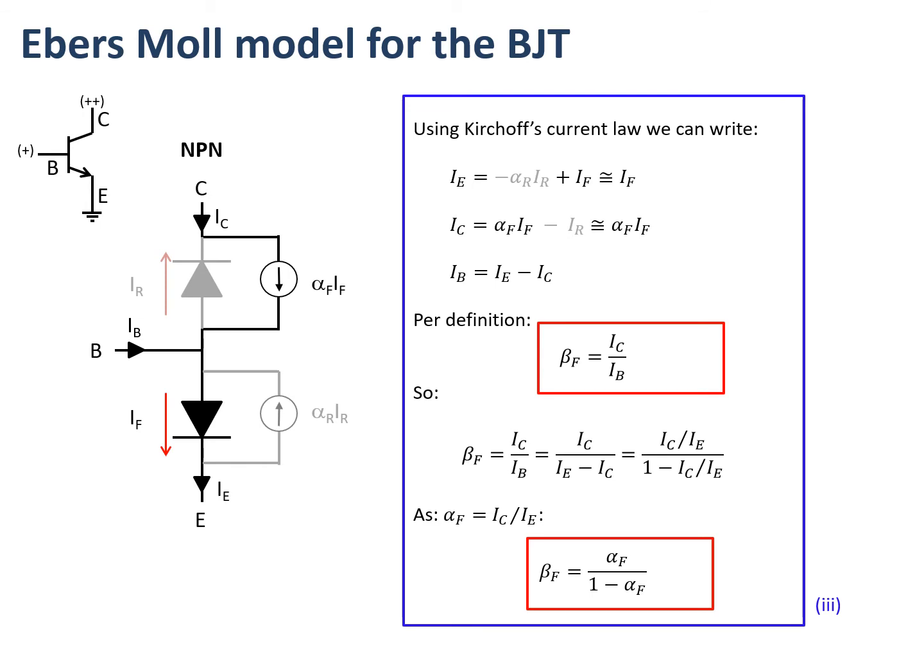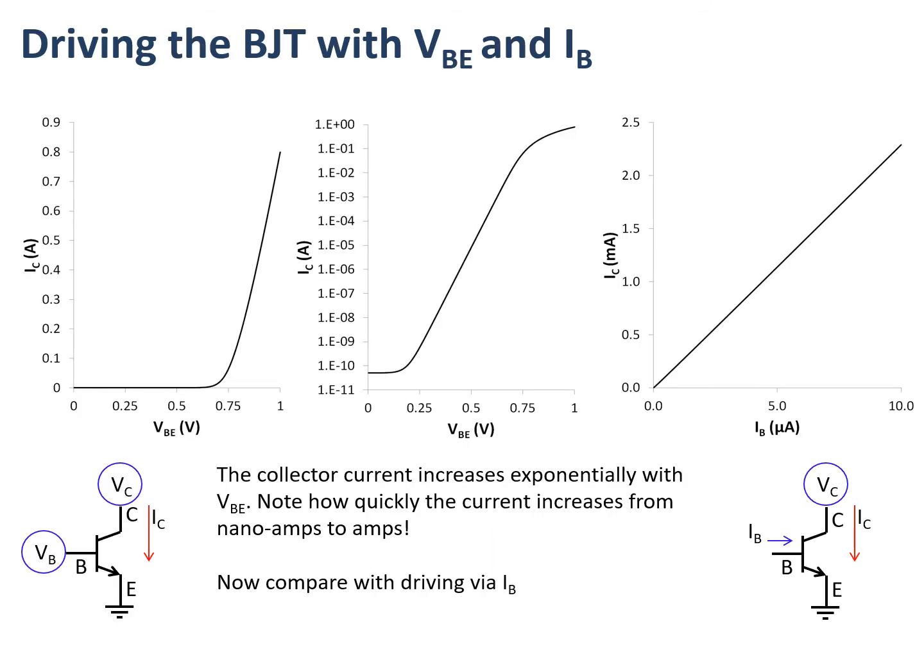But as I've said, generally in a circuit, we're mostly interested in the beta value, and that will typically range between 100 to 200 in most common bipolar transistors. Now that's given us some basic equations which we can relate the different currents of the bipolar transistor to each other. And let's have a look what happens when we use a bipolar though, and we start to drive it and we start to connect it up to measure the currents that we see.